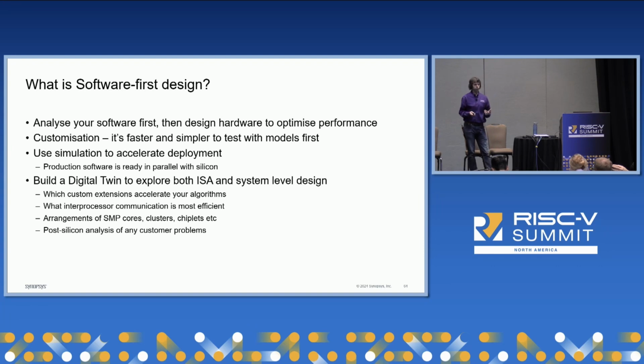If you want to look at customization, it's faster and simpler to test with models first. It's much, much easier to add custom instructions into a model and do some profiling than to develop RTL, verify your RTL, and use that to prove whether those custom instructions are worthwhile. And if you use simulation to develop your software, you can accelerate your deployment as well.